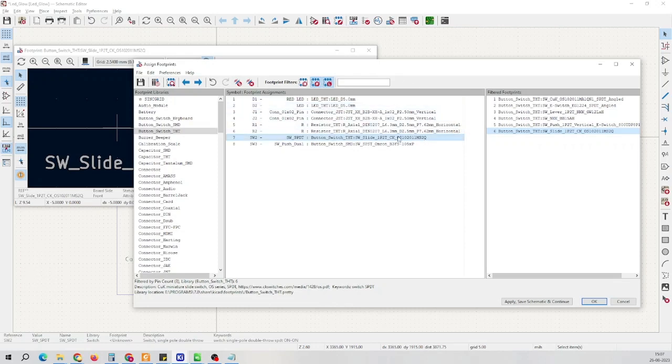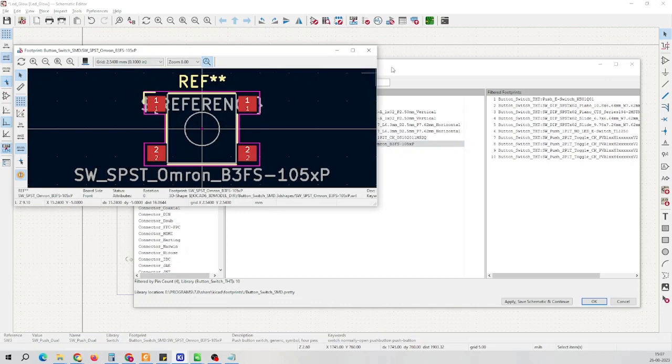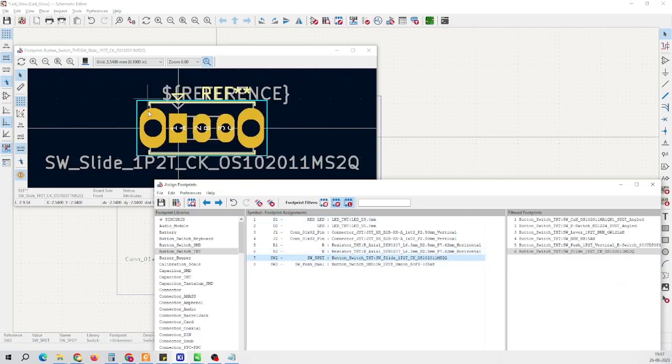Okay. So with the rest of the parts, this is another option that was pre-selected by KiCad. But as we know, for SMD components the pads will appear in red color, but for through hole components the pads will be visible in yellow color.